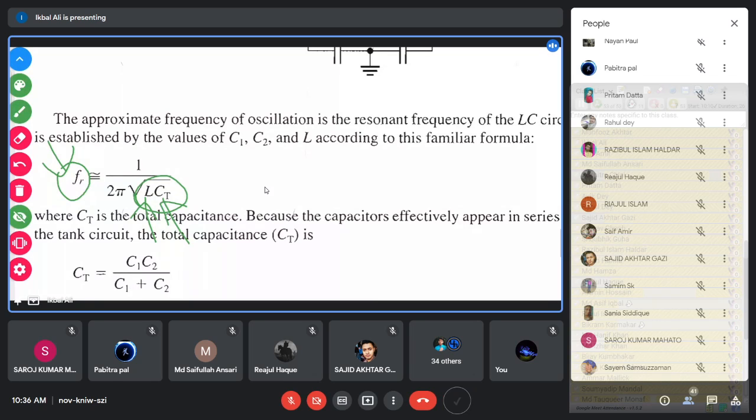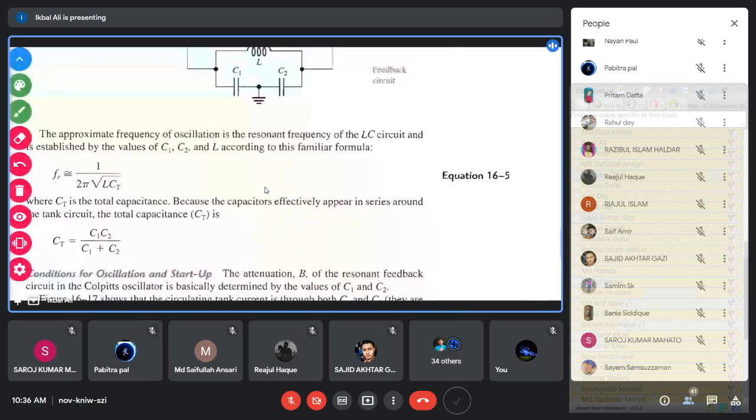So that is why fractional resistance is meaningless. Resistance value usually cannot go beyond a very low value. That is why such an oscillator does not produce a very high frequency signal. You have to replace the resistance by the inductor. Your beta network should be inductor and capacitor. Then it can generate a very high frequency.